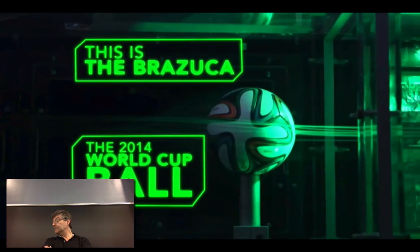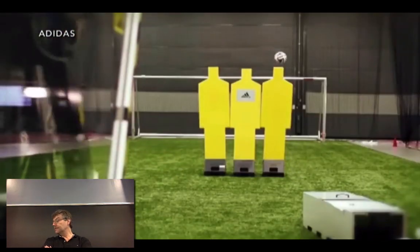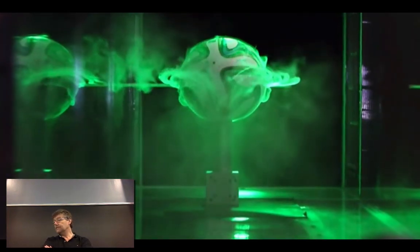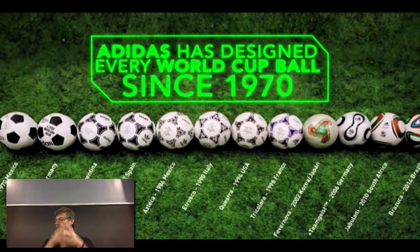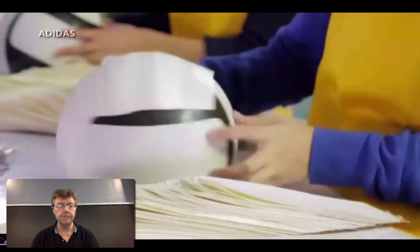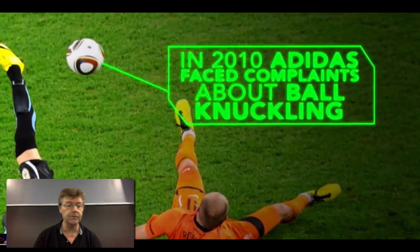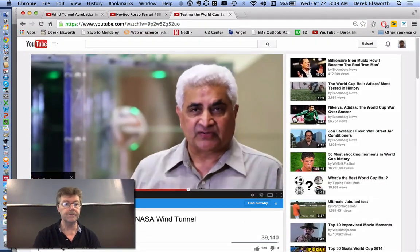Although the interesting thing is, as we'll find out, the reason that golf balls are actually dimpled is that you want them not to be smooth. A smooth golf ball would probably not go as far as a dimpled golf ball. The reason for the dimples is that it sets up a kind of boundary layer, which makes this turbulent thin layer around the ball, which allows it to go with much less drag, and therefore it can be driven further. And so the reason for dimples on a golf ball, perhaps there are dimples on this soccer ball as well, is related to that. So it's some interesting, counterintuitive components of behavior.